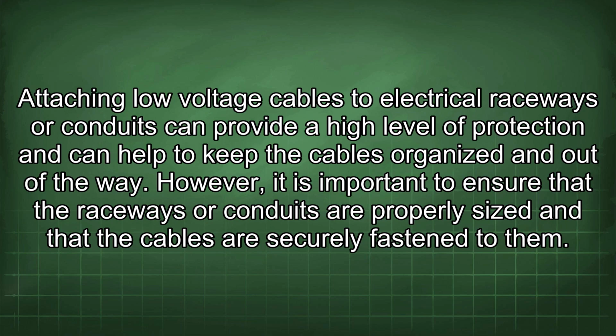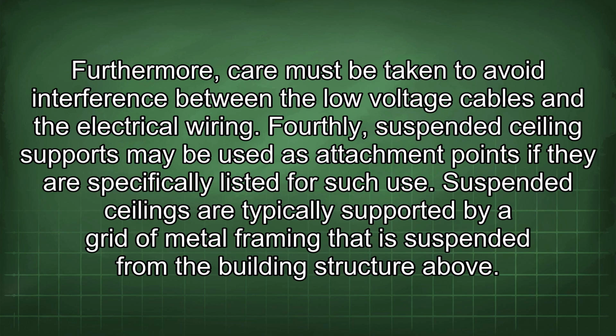However, it is important to ensure that the raceways or conduits are properly sized and that the cables are securely fastened to them. Furthermore, care must be taken to avoid interference between the low-voltage cables and the electrical wiring.